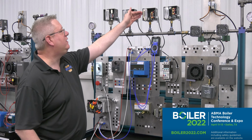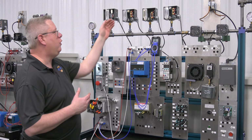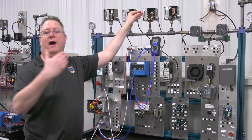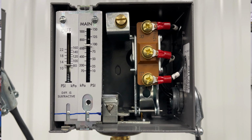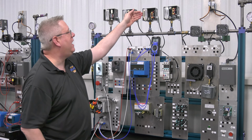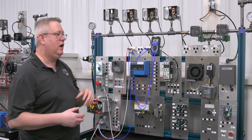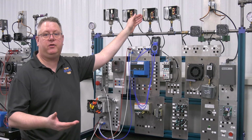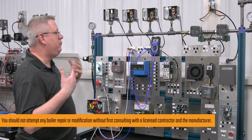So I do like it set enough higher that I could walk in the boiler room, and if the boiler is normally off at 100 psi, I can clearly see that we're at 115 or 110, and that would cue, hey, we need to check our operating control. Also, if we do have to reset our manual reset, we want to check our operating control operation, because it may not be a fluke that it tripped. We could have a blockage or an issue with our primary pressure cutoff.